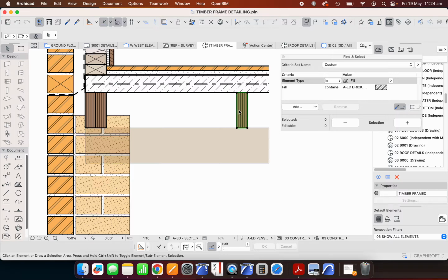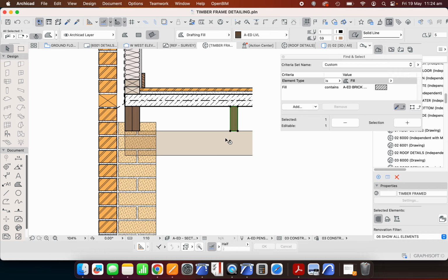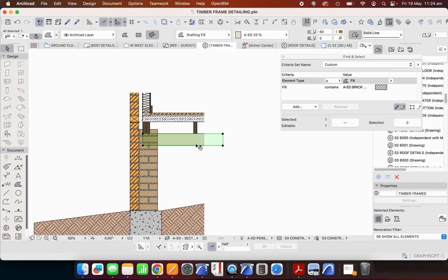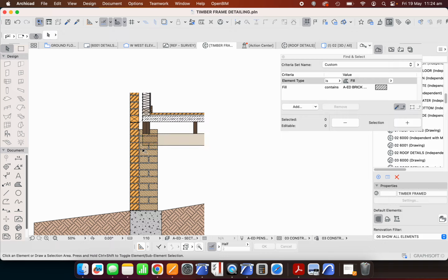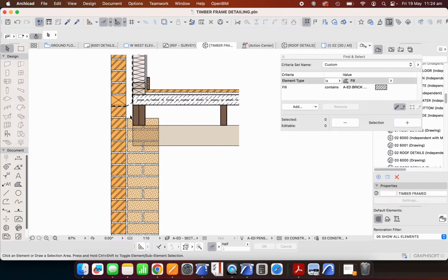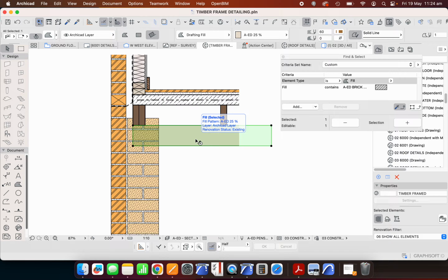So these joists span continuously over the bearer, and then this bearer needs to span continuously over the engaged pier, and then isolated pier, and then isolated pier, all the way through to the other side of the building, hopefully, where we've got another engaged pier. And of course, if I can't get the bearer to span that far, it's okay if it spans at least between 3 elements, 3 piers, and that would allow for a continuous span. If it's only spanning between 2 elements, that would be a single span, and therefore it wouldn't be able to span as far.